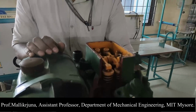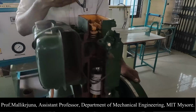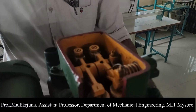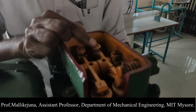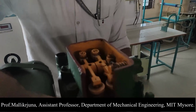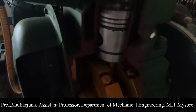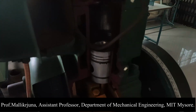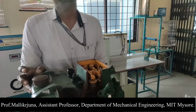I am giving the momentum now. Now this is the inlet and this is the exhaust valve. If you clearly observe, the exhaust valve is getting opened, but still the piston has not reached BDC. I can show you that. Now you can look onto that. The piston hasn't reached BDC completely. That can be seen by the piston movement, or on the reading also you can observe it. The reading hasn't touched the BDC mark yet.